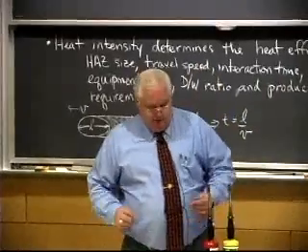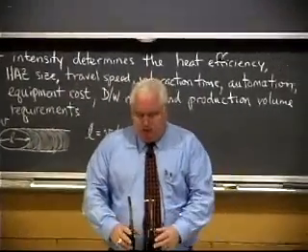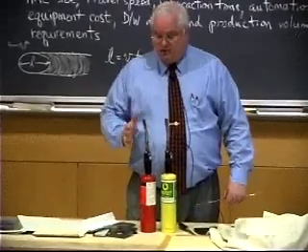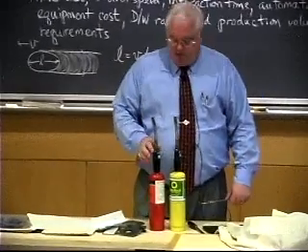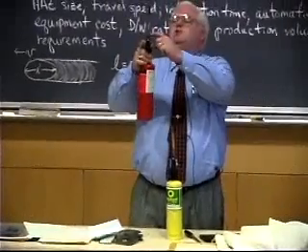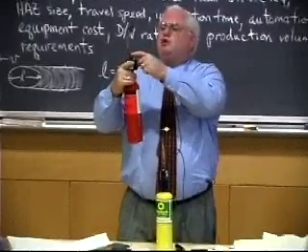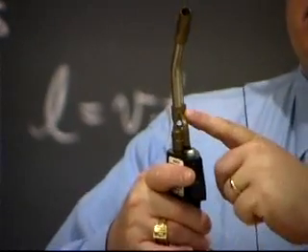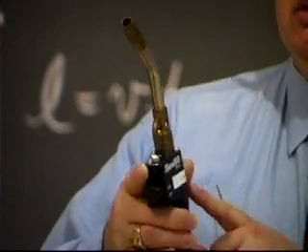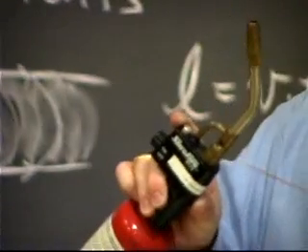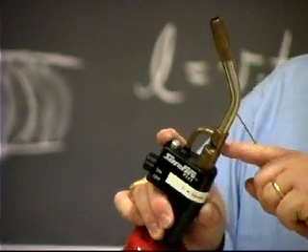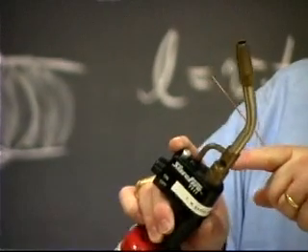an air burning flame. Now, what I have here to illustrate some of this is going to be an air burning flame. In fact, if you look carefully at these torches, you'll see there's little holes down here in the torch. And what happens is the fuel comes up through here. There's a small little hole, I'll pass one of these around later, that creates a jet of gas coming right through there.